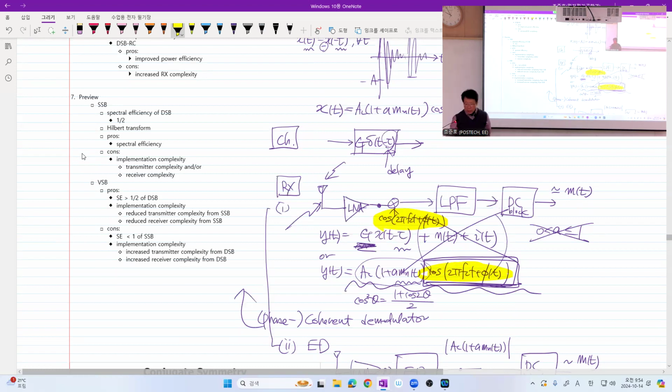Okay? If I make an analogy, you have a target, and you not only have wide spread, but also your mean value has an offset. Got it? If you understand my analogy, that is the carrier frequency offset, not only the phase noise. So having a coherent demodulator at the receiver may be very costly.